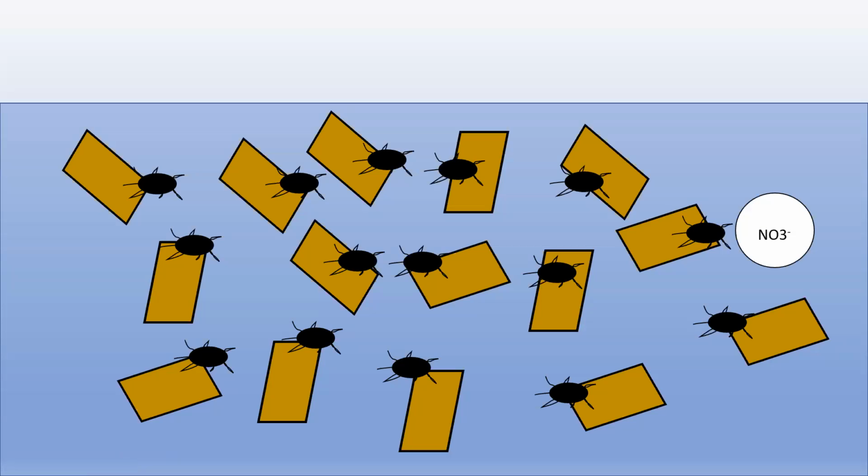That nitrogen, that's going to be the interesting stuff. So nitrogen, we all know how active that is in the environment, how much it's going to cycle, how it changes between forms very readily. So when you've got nitrate in these water systems, very soluble form of nitrogen, what we want to do is we want to get that out. So nitrate, how do we get that out? One option is denitrification.